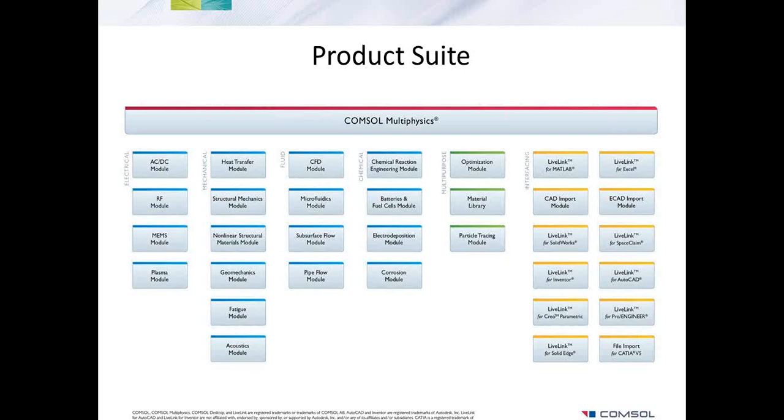Okay. Fanny wants to know, can I model multiple layers of different materials? Absolutely. It's very similar to what we did in our demo model. Just like we had a head mass and tail mass made up of aluminum and steel, and then we had the piezoelectric layers, and they were even reverse polarized and all that. So even if you have a flat structure, like a MEMS structure, with multiple layers of different materials, you can absolutely go ahead and do it.